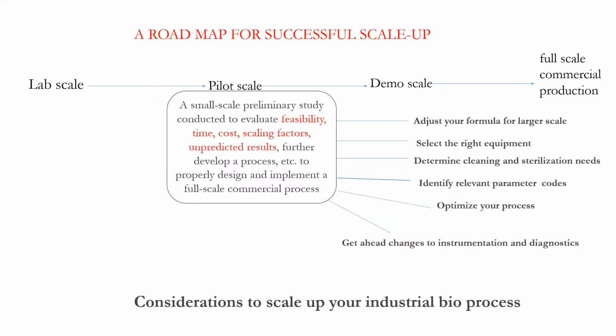What will happen if you are going for a submerged fermentation and you choose a process in which proper mixing is not done? In some submerged fermentation, you have to have proper agitation. So if you choose equipment that does not have a proper impeller, your production yield will be hampered. So you have to choose the right equipment depending upon your desired end product.